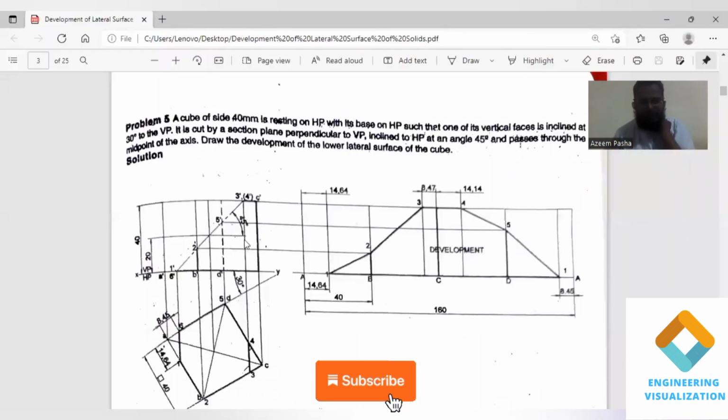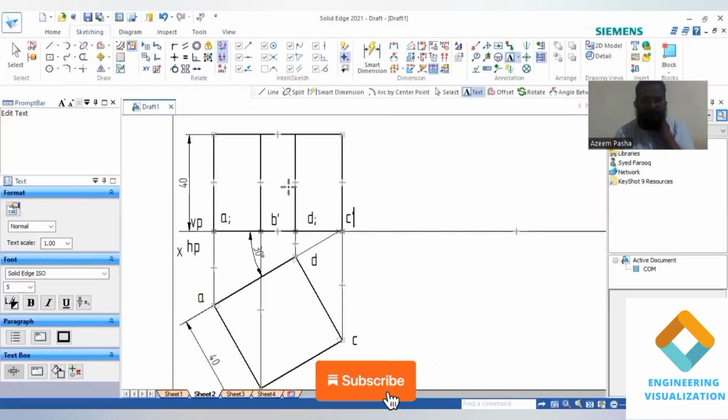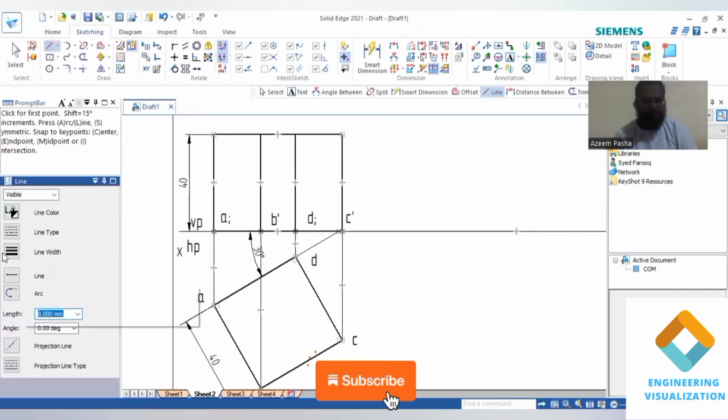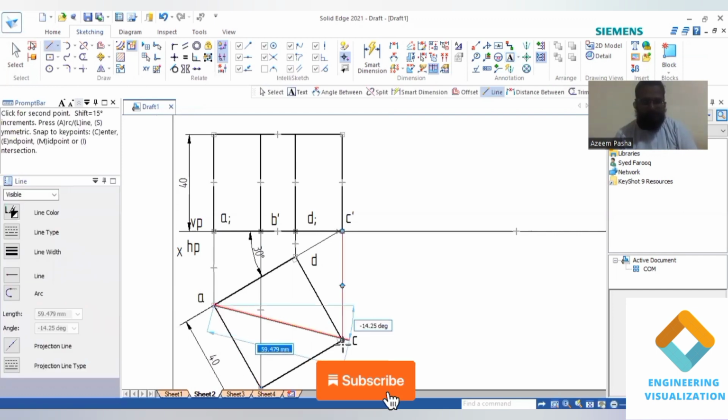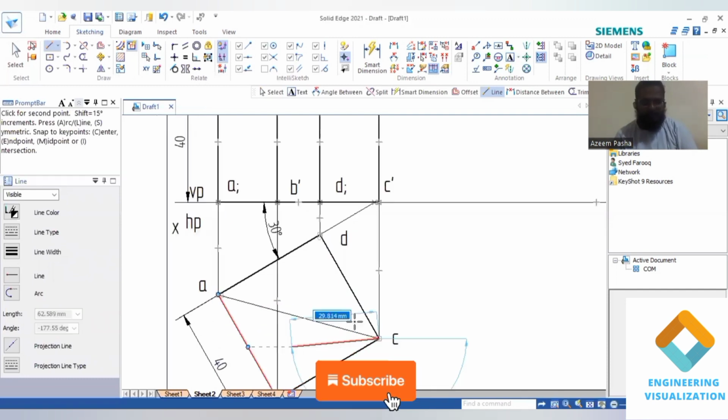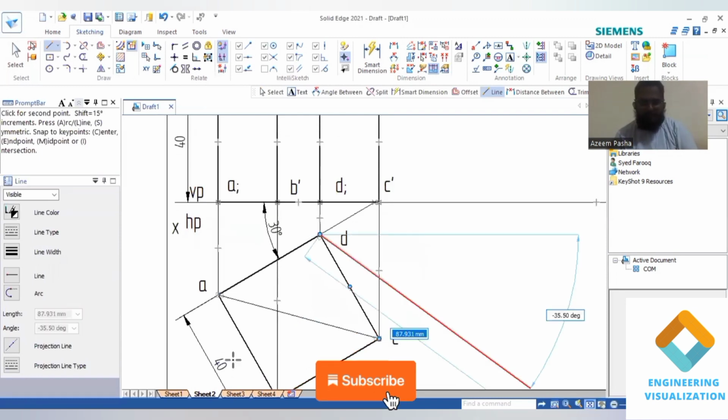Now you can see here we have to draw an axis. For that I'll be drawing thin lines here, that is diagonal lines, to find the center. Then I will draw an axis in the front view also. I will draw a thin line here because it is a prism. So the cube is one of the prisms, so remember it: the inside lines we are drawing should be thin lines.